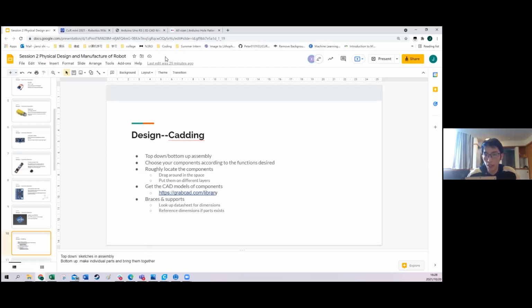So basically, whenever designing something that's symmetric, always try to use a line of symmetry in the middle and mirror everything from left to right. It's also very helpful when you're assembling, because you can use the central plane for a lot of the mating.